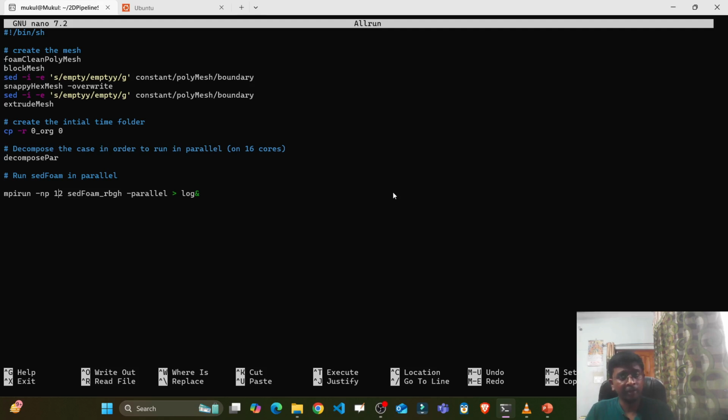Then one day I decided that I'm just going to remove this. For 48 hours I think I only took 2 to 3 hours of sleep. I think I had not eaten much, but I wanted to find what the error was and why it was not running, because I was pasting this whole line also in the HPC slurm file. What was happening? This ampersand, why do you put this ampersand in OpenFOAM?